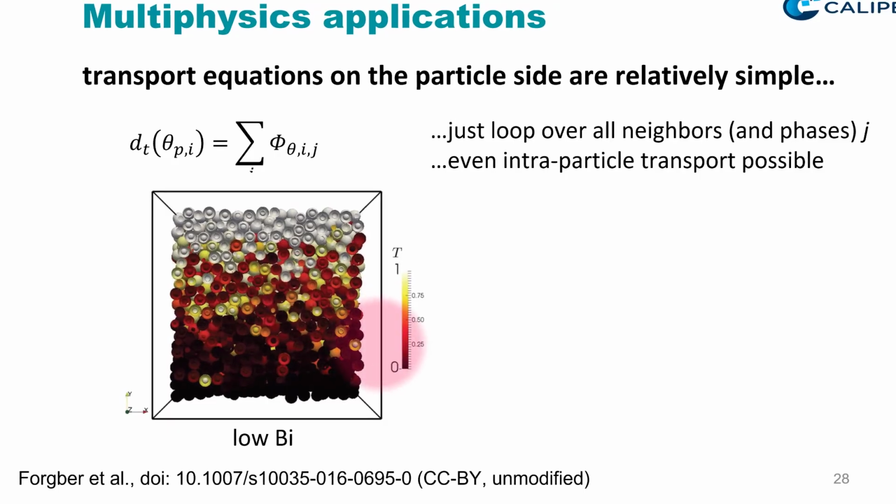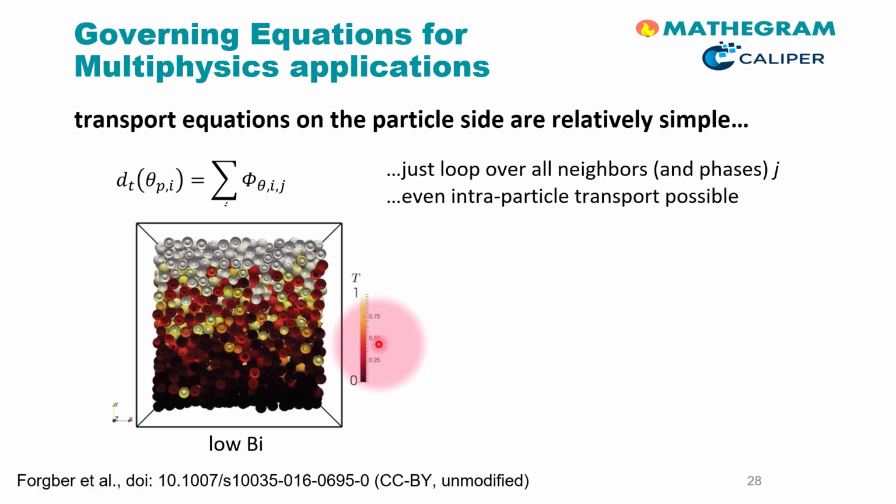The per particle temperature fluctuations that you see here are caused by the relatively large particle speed in this case. You will see in their publication that a high Peclet number was used for this purpose, which means that convective transport due to particle motion was stronger than heat conduction.